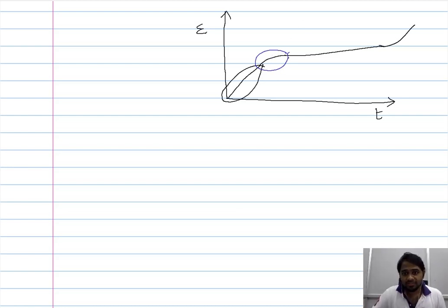And the stage that follows the transient creep region is a state wherein the deformation or the strain is rather minimal, and the rate at which it occurs is also minimal. So there is only a marginal amount of deformation that is observed in this particular stage, and this stage we refer to as the steady state creep stage. And the final stage, wherein there is a significant increase in the rate of the strain, we refer to as the accelerating or tertiary creep stage. So we have primary creep that includes instantaneous and transient creep. We have secondary creep that is largely steady state creep, and finally we have our tertiary creep, which is also an accelerating creep.